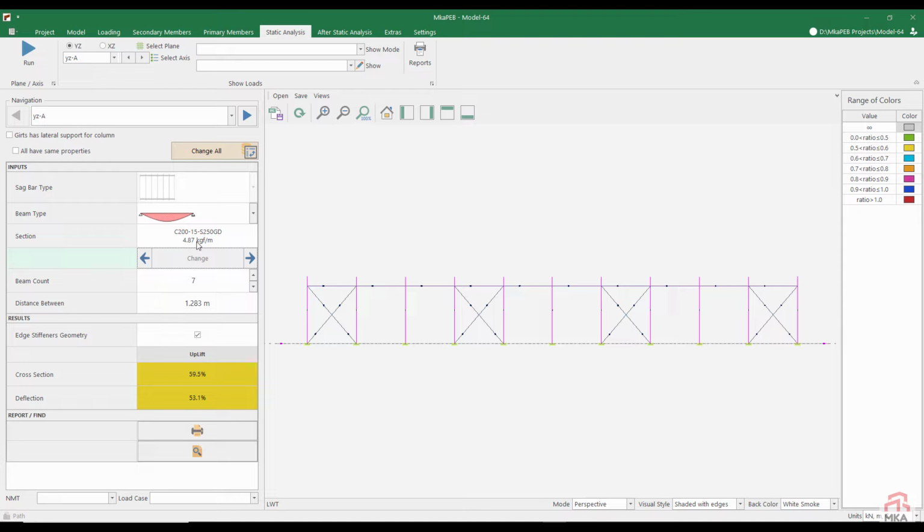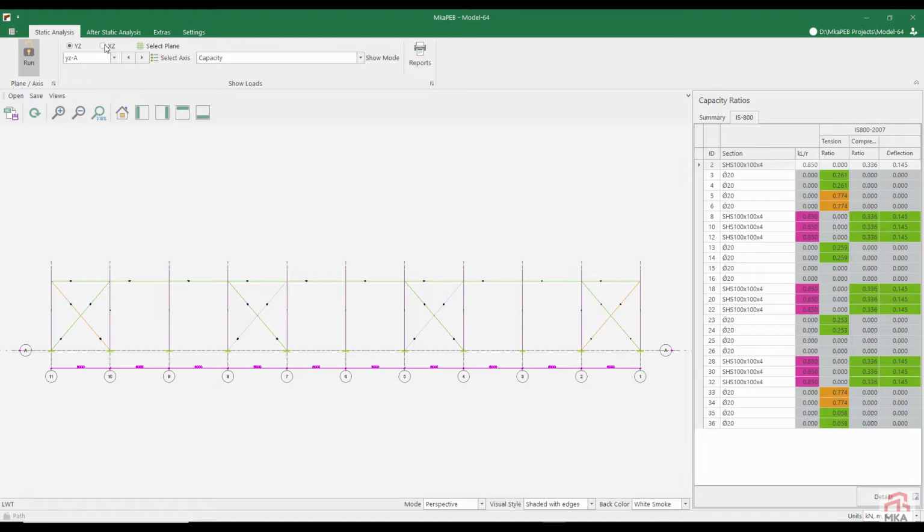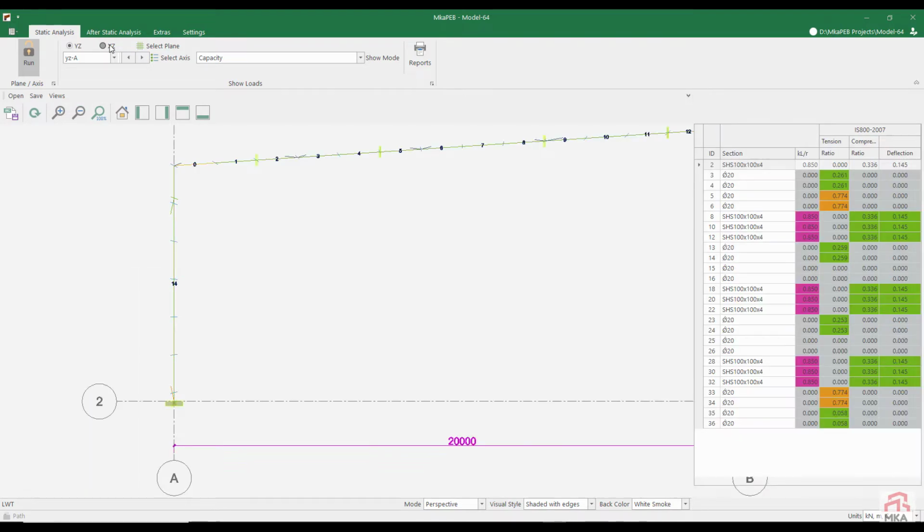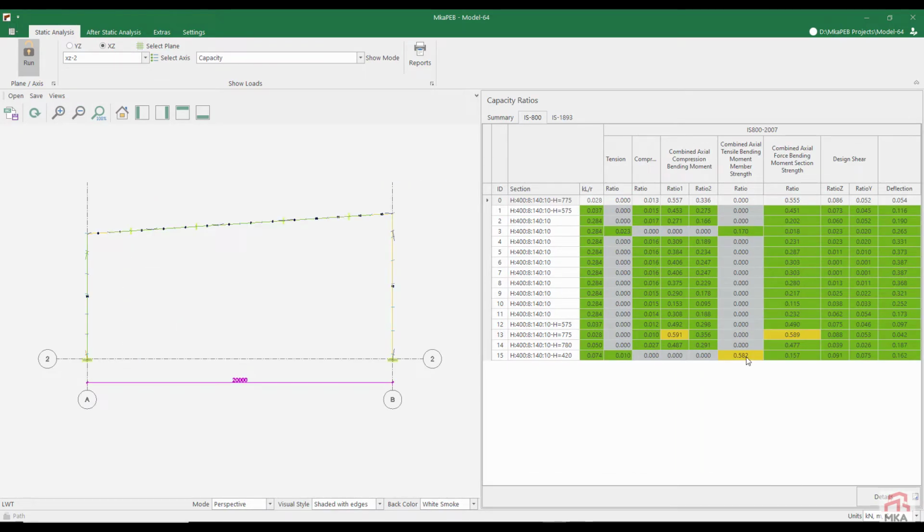150 by 20 or 200 by 15, which is better? This one looks lighter. I looked at the other side. I'm replacing it with the same cross section, I've replaced it with 200 by 15. We have a capacity of 58% in the columns we have chosen. I think these are the column sections 14 and 15.